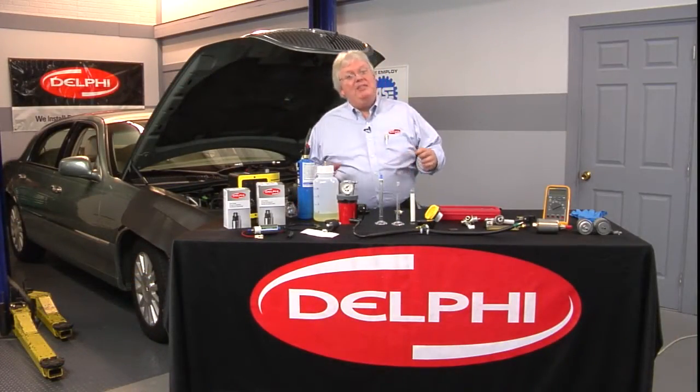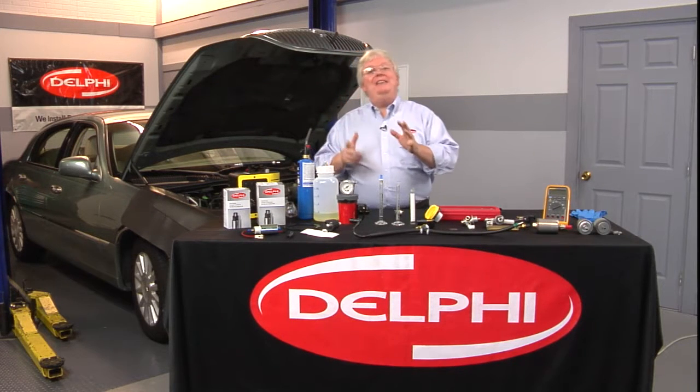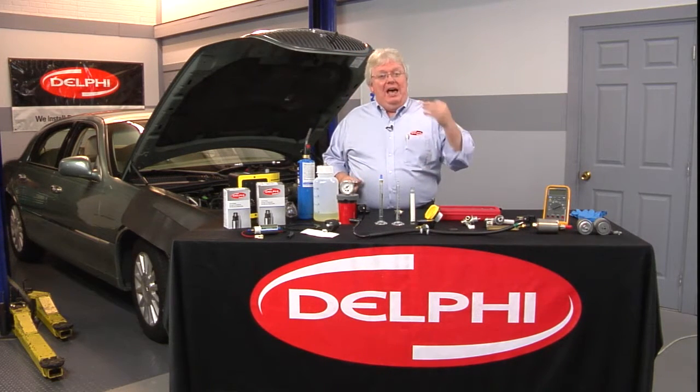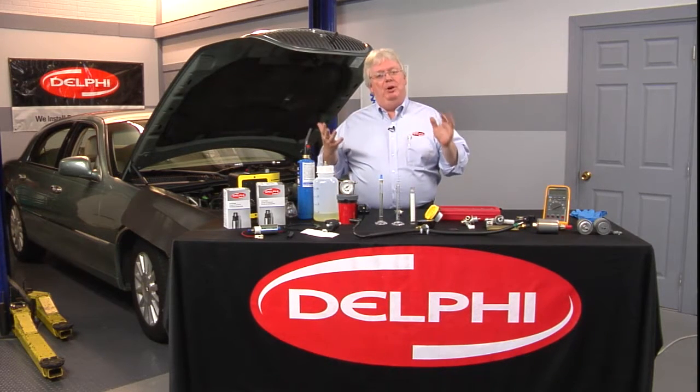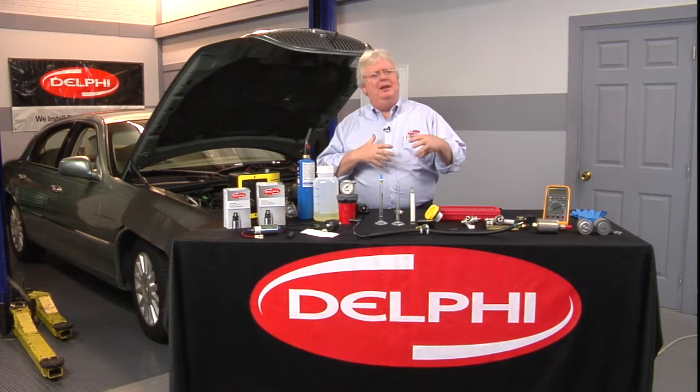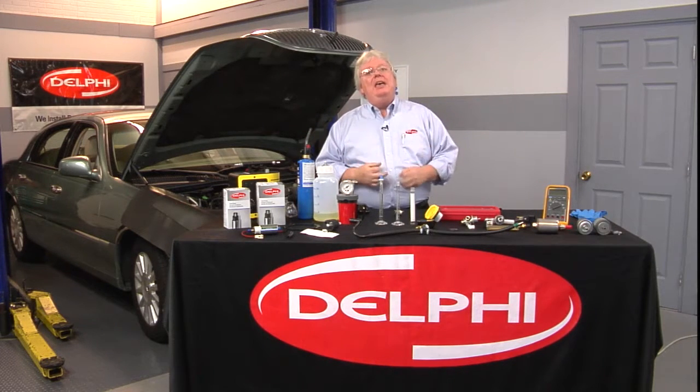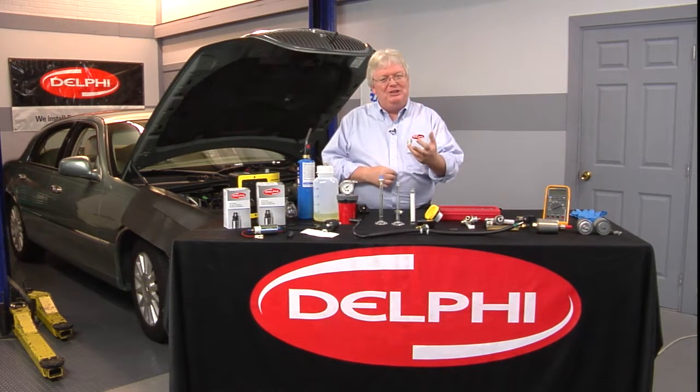One last point I want to make, and then we're going to open up to questions from you guys in the field, is the side of the mechanical nature of the engine. Now, if the engine has any aftermarket components, a bigger throttle body, a different camshaft and a different intake, it's going to affect volumetric efficiency and it's going to affect fuel trim unless it's had a calibration update to go with the performance parts that have been put in the engine.